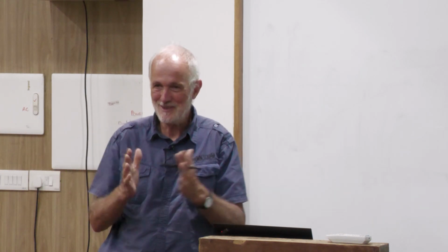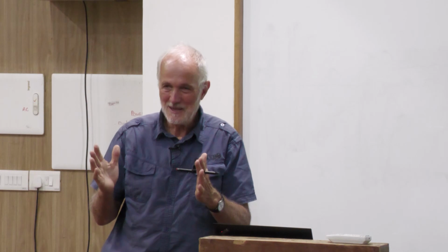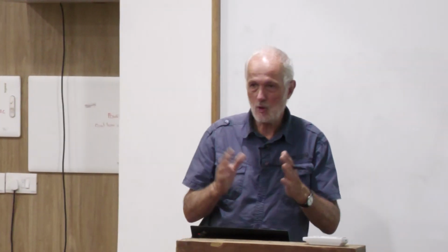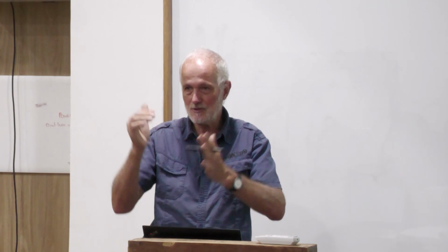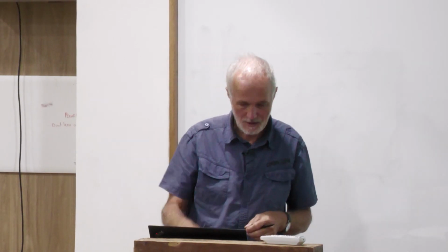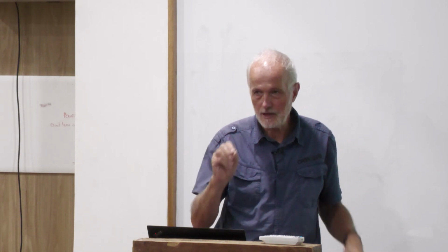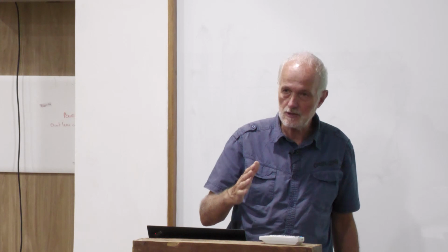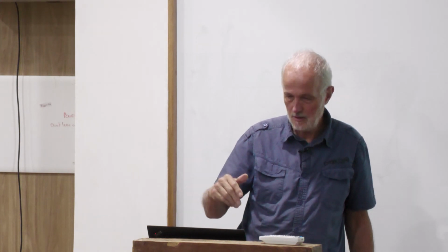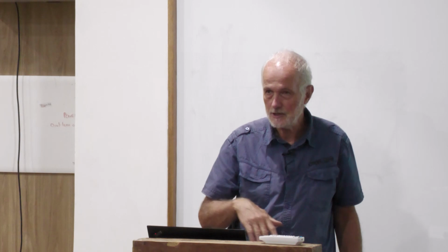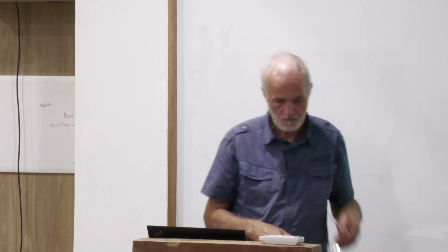Yeah. Just, for FCC it's a bit boring. It's mostly only the lattice parameter. But for a tetragonal phase, it can be the A/C ratio and all these things. Or if you have more complicated intermetallics, perhaps the relaxation of the atoms. And in particular, of course, if you are studying defects, if you put a vacancy, how much do the atoms relax around the vacancy? All this I mean by structural relaxation, energy minimization.